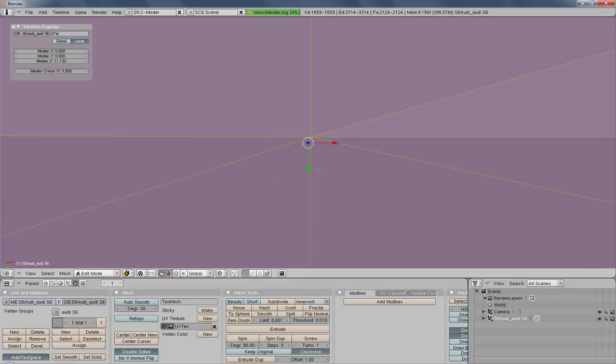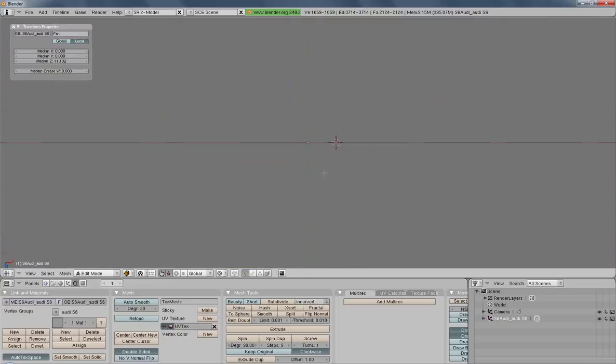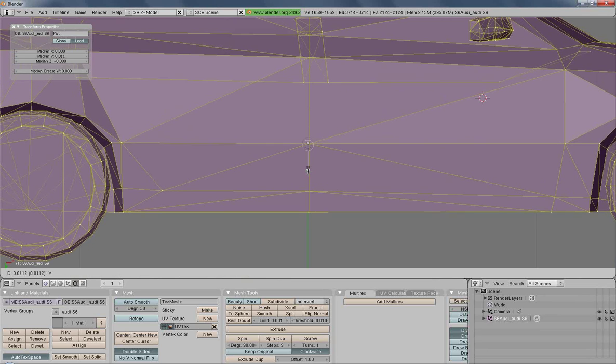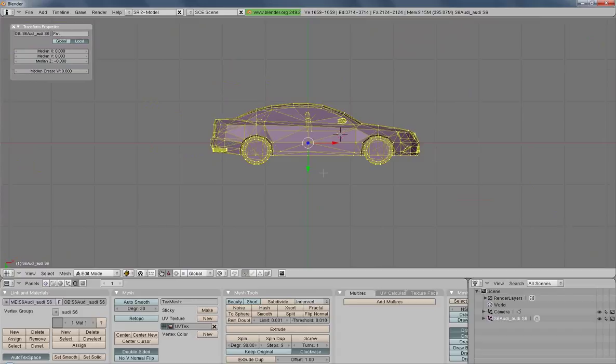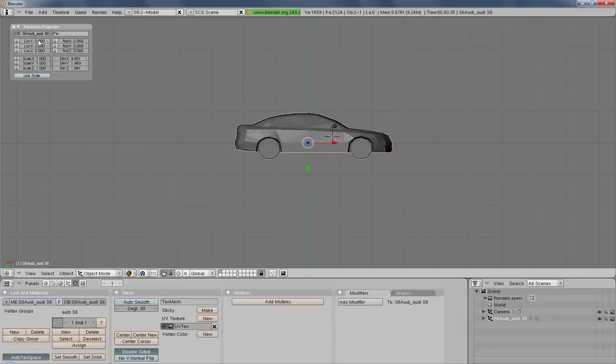So now X and Y are overlapping, and I will rotate by 90 degrees to also bring the Z-axis to an overlap here. And again, move it down. Okay, so going back. As you can see, it's still in the center here. Okay, so now we have a look back in the object mode. Now we have deleted all the translation information and the rotation information, and we have scaled our car to 1:1:1, which is quite important for the use in OpenDS.